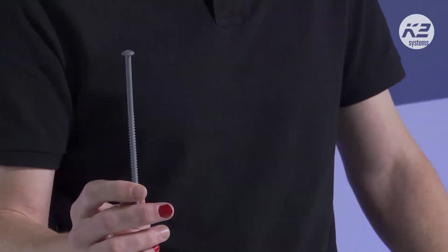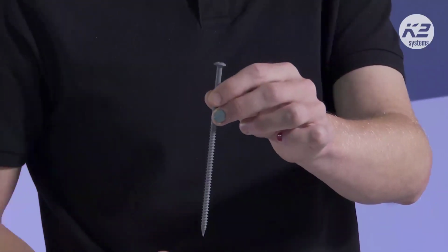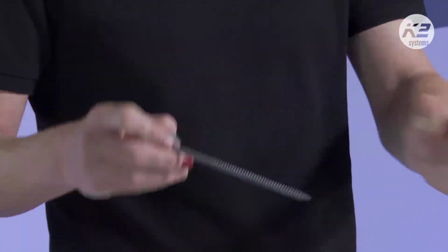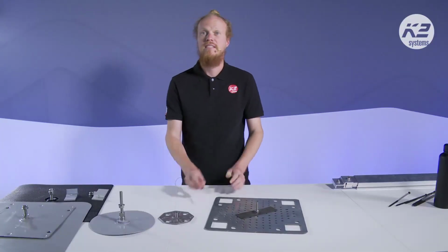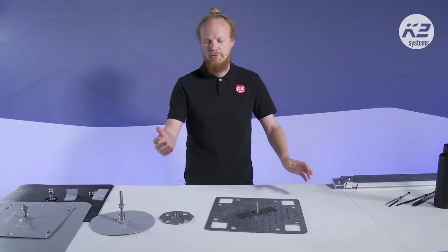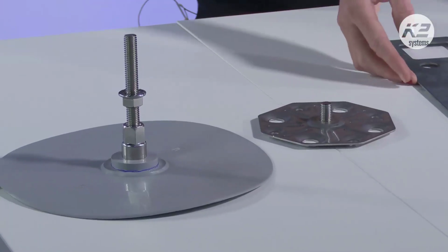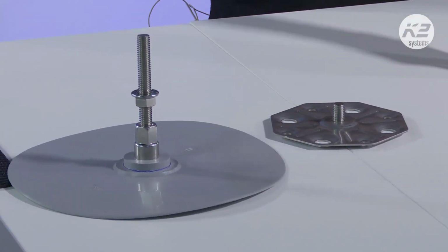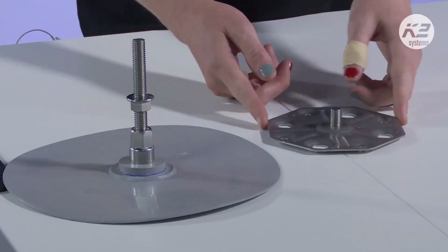There we go. An insulated membrane where you want to screw into the under construction, usually a trapezoidal sheeting. But you could also have wood screws that just fix into the top layer. This idea of fixing is common, although a little bit different in different places. For example, a different hook that is used is the Sika anchor. This comes with sometimes 2 or 4 screws. Generally we're doing our calculation with 4, but the idea is pretty similar.